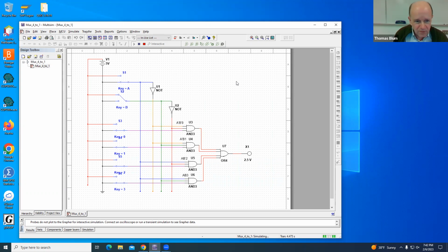Okay, so now I will move on to address 2. So switch B and A. Now A is high and B is low. If A is the 2's place, it's 1, 0, which is 2. So I'm selecting now the data at address 2. The data at address 0, no effect. 1, no effect. 2, that's causing the blinking. That data is now getting through.